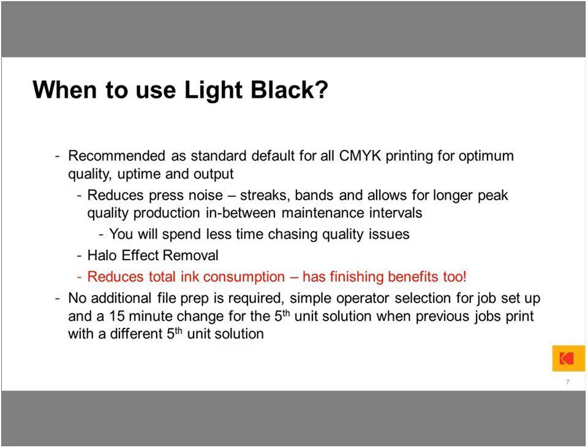You'll also see some benefit with less ink on the sheet. You have a better shot at controlling your hot offset, which those of you that know what that is, we've talked about in other webinars, and I've spoken in detail about how the temperatures on some of your sheets may be a little on the high side, creating some hot offset, which will cause contamination and dirty up the oil and cause some quality and streaking issues as well.